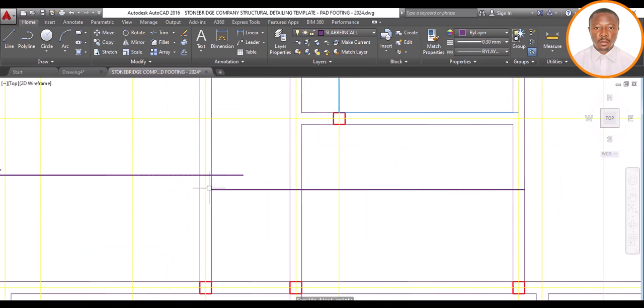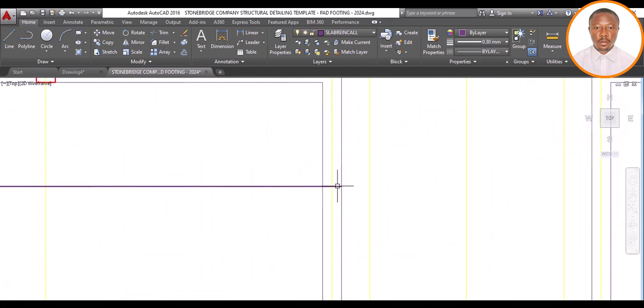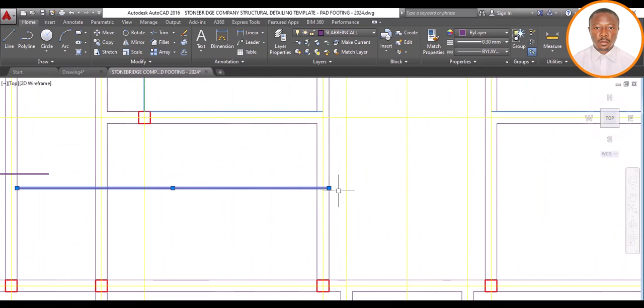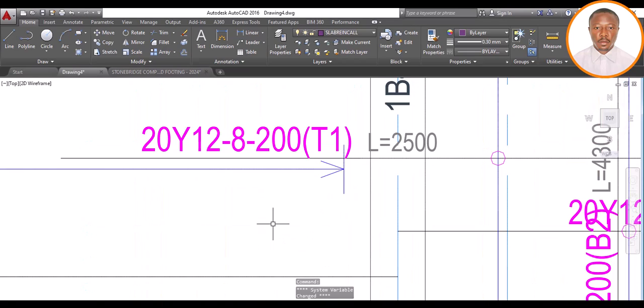So at this point here, I don't need to have my return bar because it's still within the slab. What I need to do, at this point too, you can still enter this slab. So what I'll do, I'll move it by what? 600. Remember how we got our 600 into this particular slab. Is that okay? So now, this reinforcement, this one from here on this axis, I'm done with it. You can see how fast it is compared to what Prota detailing was giving us.